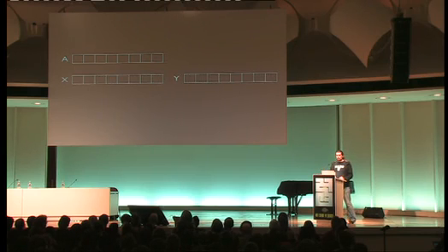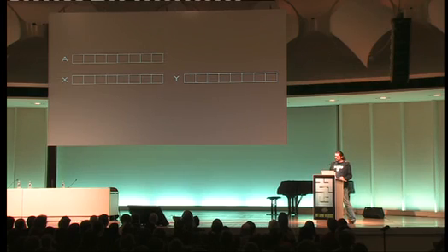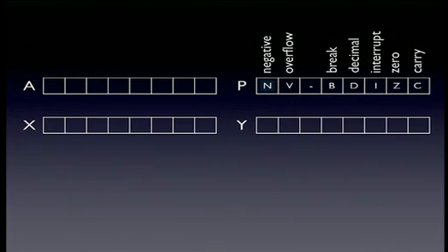And the index registers, which aren't as powerful, can count up and down and be used as an index in accessing an array, but you cannot do any arithmetic or logic on them. You have the processor status register. It's 8 bits. You have 4 bits in there which are about arithmetic and logic, 1 bit which signals decimal mode. I'll talk about decimal mode later. It's quite boring. And there are 2 more bits about exception and interrupt handling.